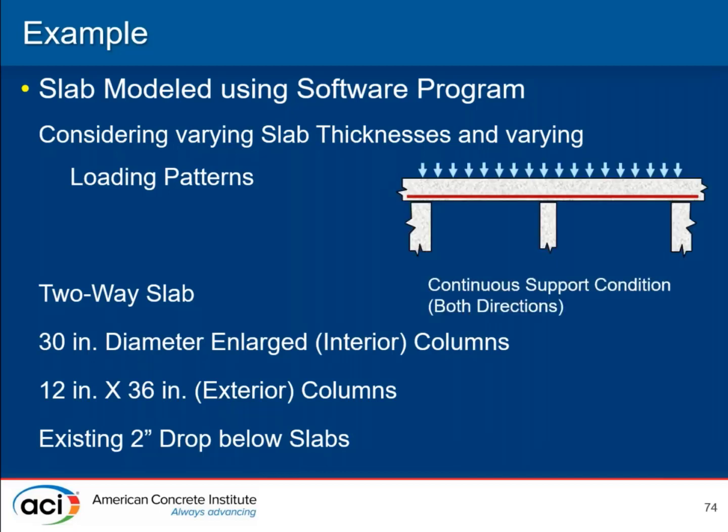So there's one of the loading patterns that we're going to be considering, with live load on both spans. As I dimly remember ACI 318, I think you also need to consider 75% live load pattern loading, with 75% live load on one span only.